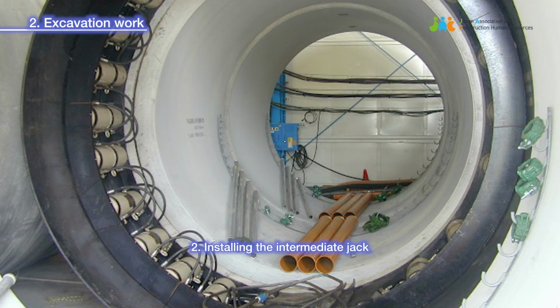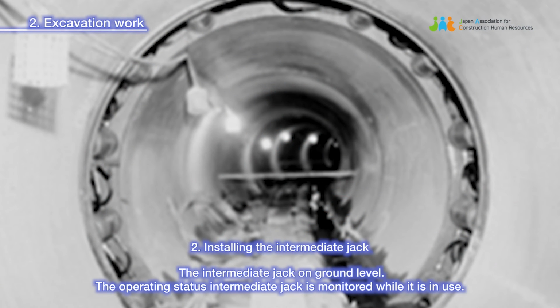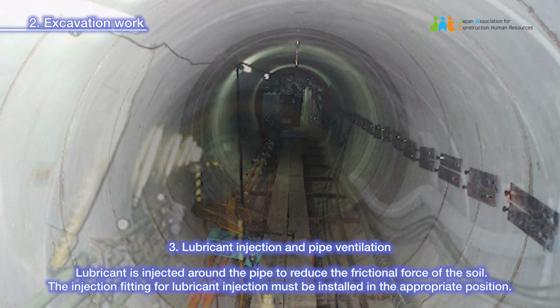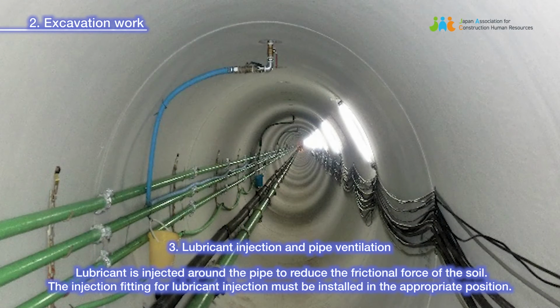2. Installing the intermediate jack. The intermediate jack is installed on ground level. The operating status of the intermediate jack is monitored while it is in use. 3. Lubricant injection and pipe ventilation. Lubricant is injected around the pipe to reduce the frictional force of the soil. The injection fitting for lubricant injection must be installed in the appropriate position.